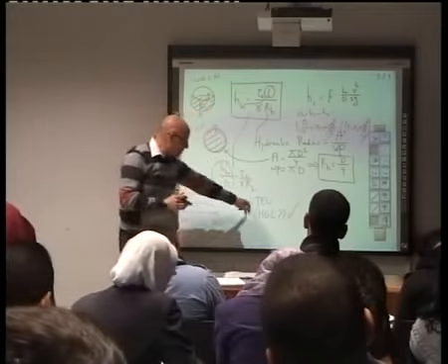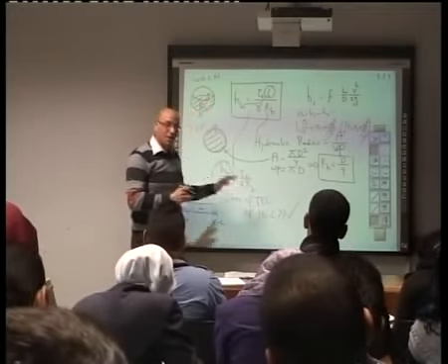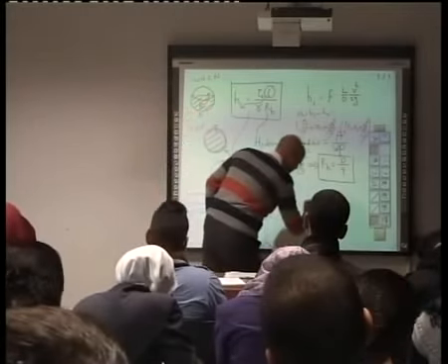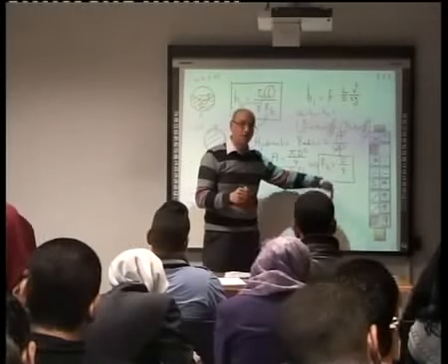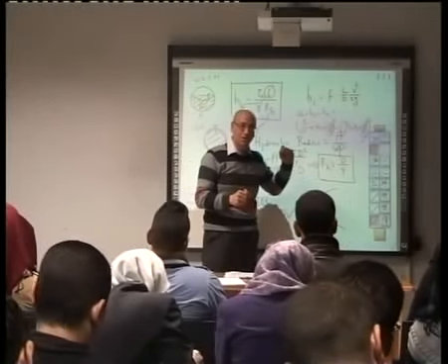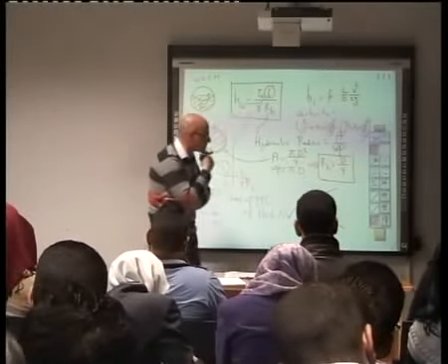In our case this is right, but if we have a pipe changing like this, it's a different story. We have to consider both situations, because in that case part of the kinetic energy is lost to an increase in, for example, pressure, and so on.